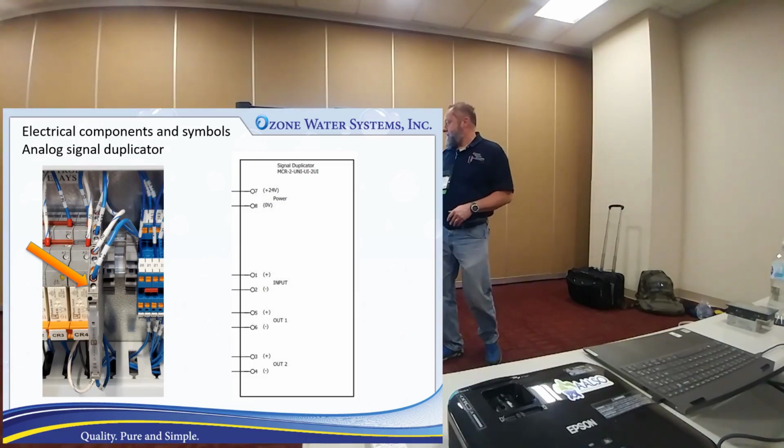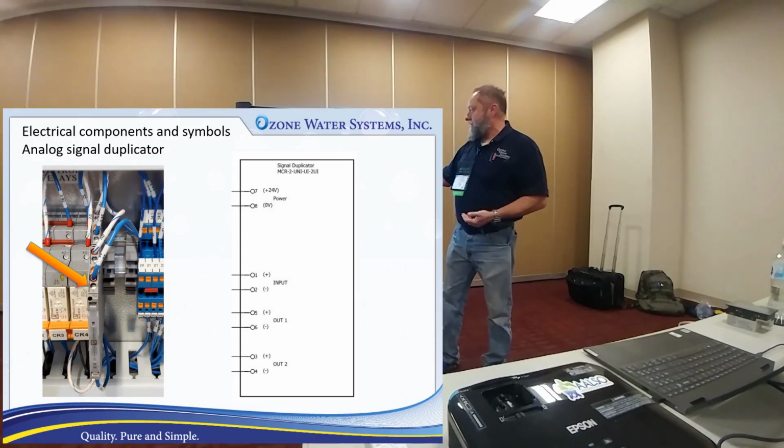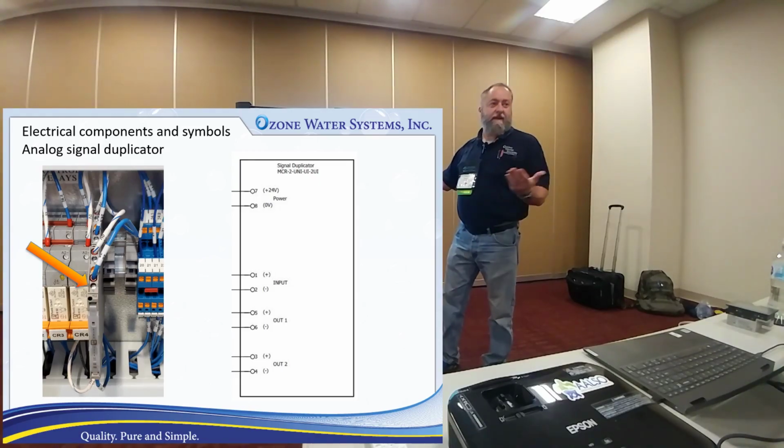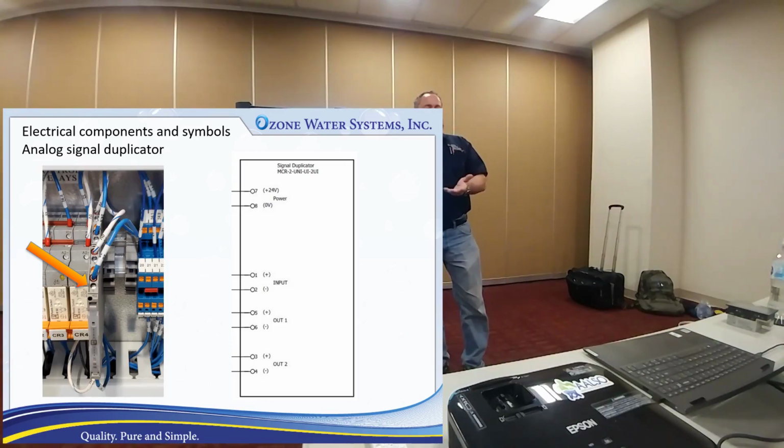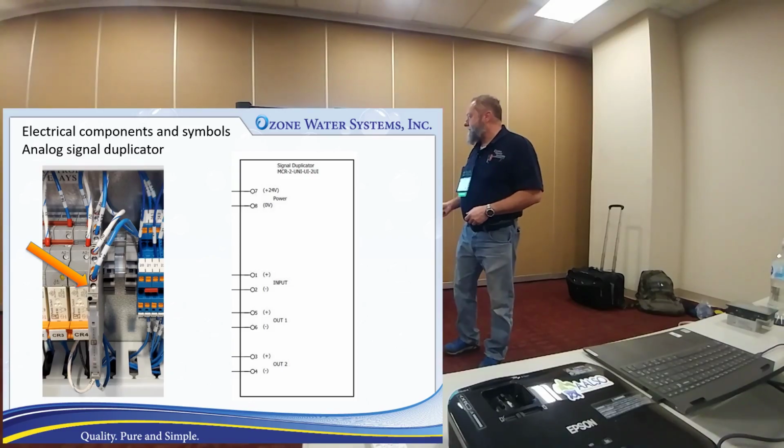If that relay, let's say you've got one of these relays and both the contacts are being used up, you could add a second relay and just parallel it, it's the same voltage. You could just run 2 relays in parallel, and then you've got 2 additional contacts you can use for whatever you want. And you can hook up some lamps to that.